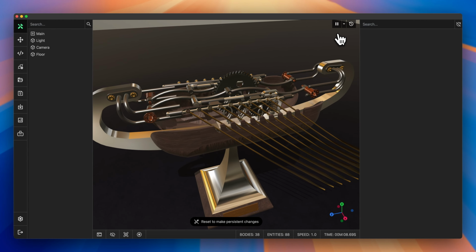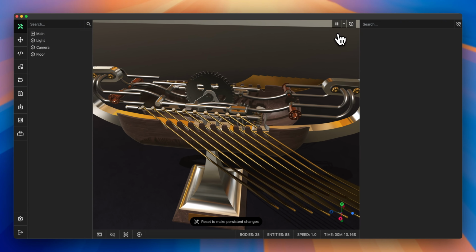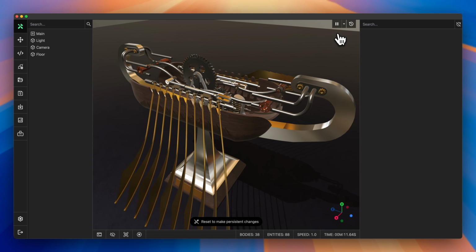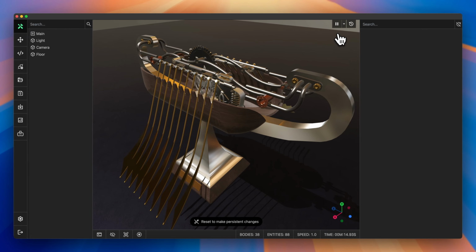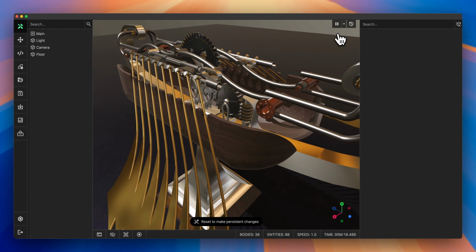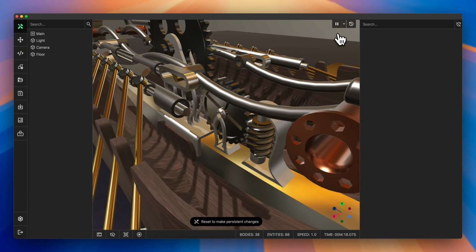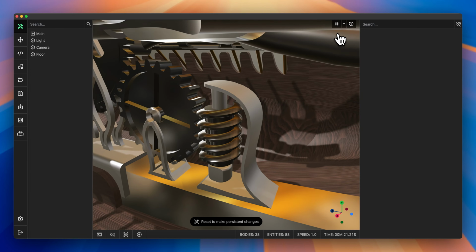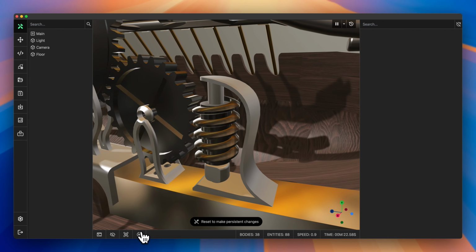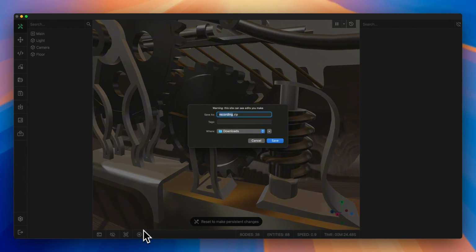In this example, I've already set up all the materials in ProtoTwin and have added an animation component to the camera entity. The animation component can be used to perform camera movements, which will get exported by the recording. Once you feel like the simulation has recorded enough frames, you can click the Stop Recording button at the bottom to stop the recording, and then save the frames to disk.